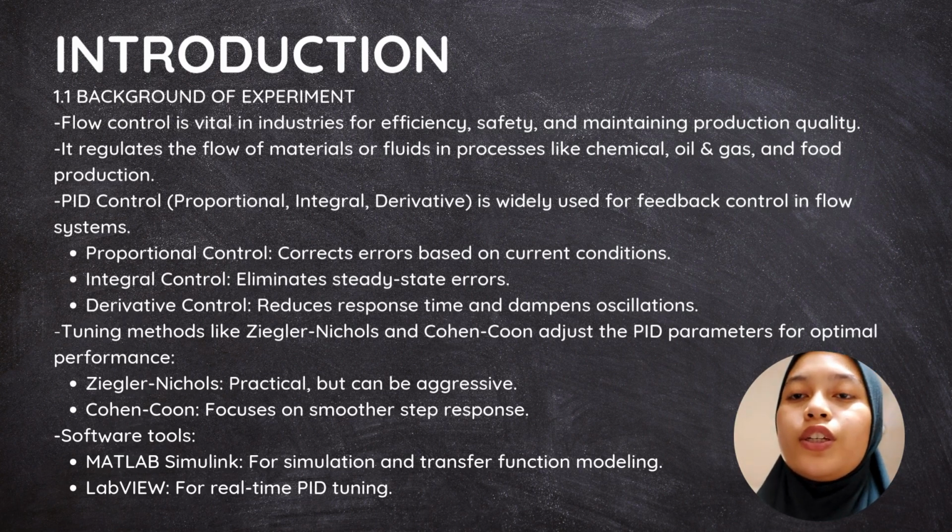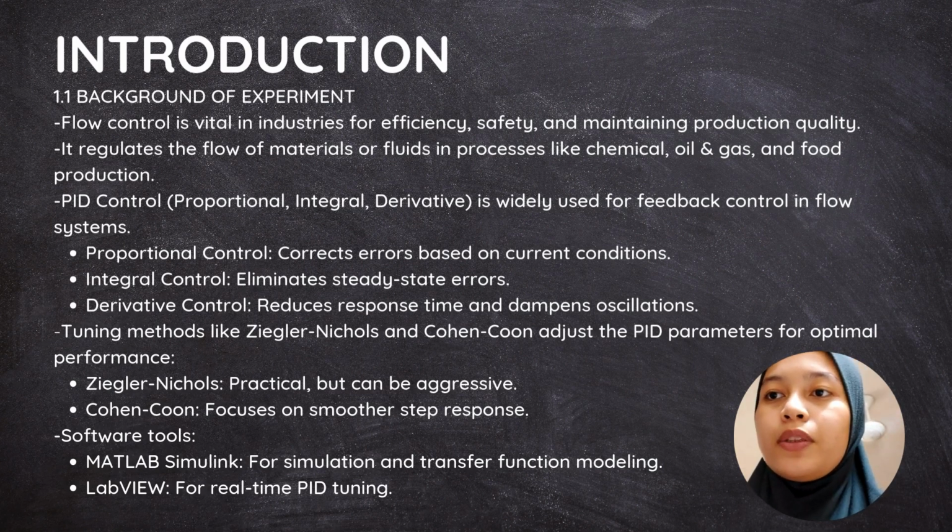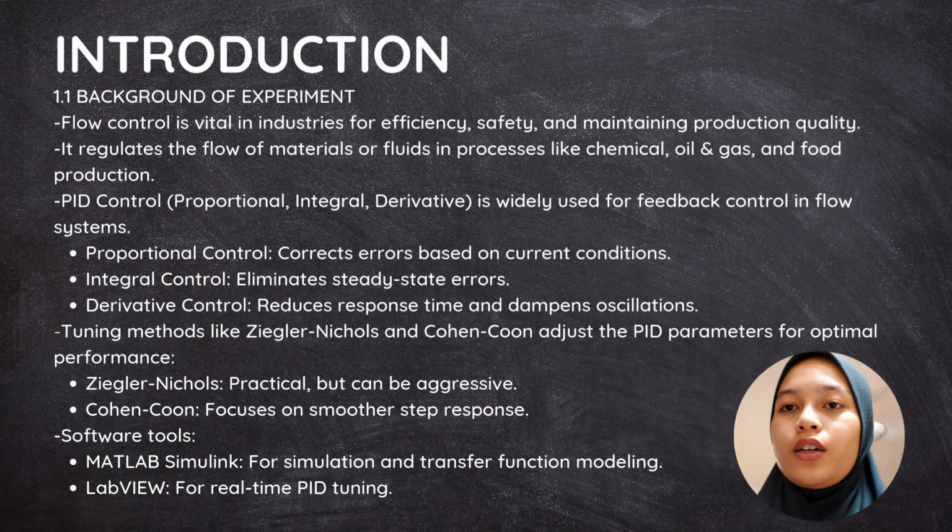We also have tuning methods like Ziegler-Nichols and Cohen-Coon to adjust the PID parameters for optimal performance. Ziegler-Nichols is practical but can be aggressive, and Cohen-Coon focuses on smoother step responses.